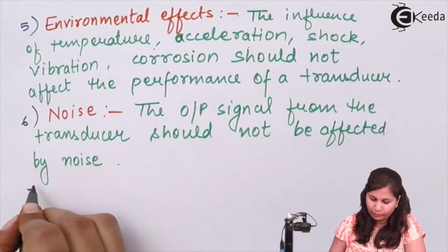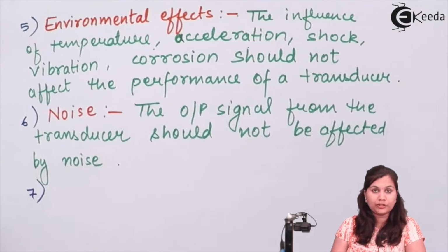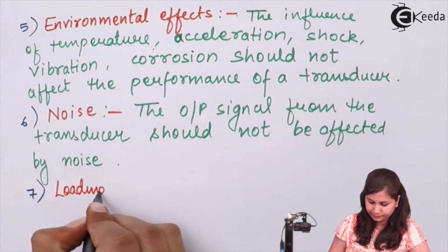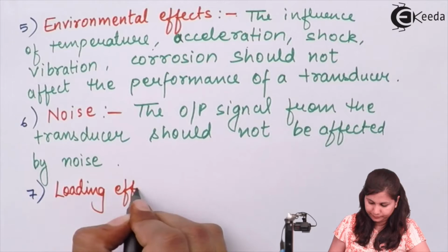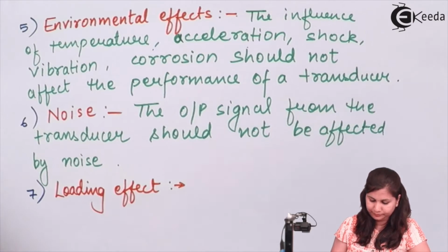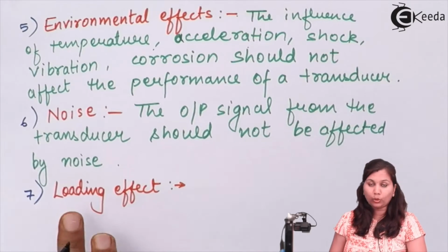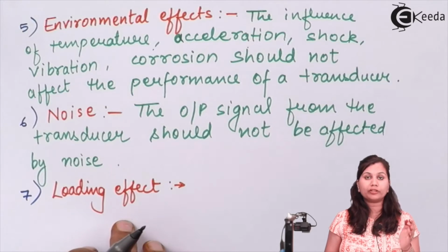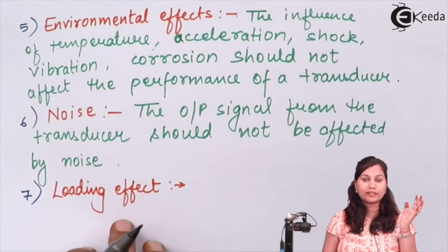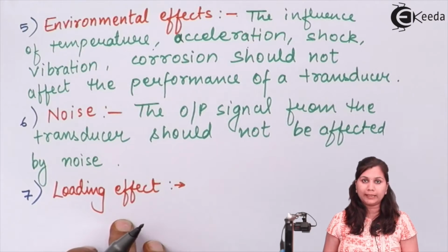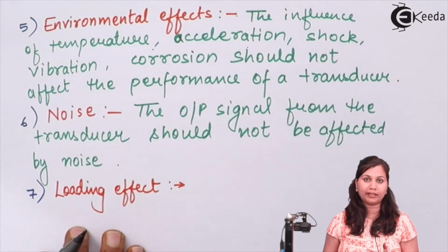Next requirement from a transducer is the loading effect. Loading effect occurs whenever the input and the output impedances of a transducer stage, or of a stage in a system, are different. Means there is no matching between the input and the output impedance. In that case, loading effect occurs.